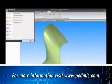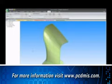And how would you get it into your CAD package? What I would do is I would select the B-splines and then select the patches, and then I could just come over here to the menu and I could go ahead and I could export those, and my export capabilities are either STEP or IGES. Okay. So what we've seen is going from a point cloud to a mesh to patches ready to be exported into your CAD program. That's correct.